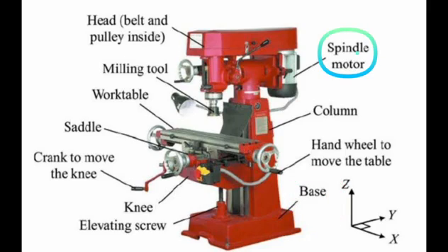The spindle of the machine is positioned vertically. The cutters are mounted on the spindle. The spindle is rotated by the power obtained from the mechanism placed inside the column. Angular surfaces are machined by swiveling the spindle head.